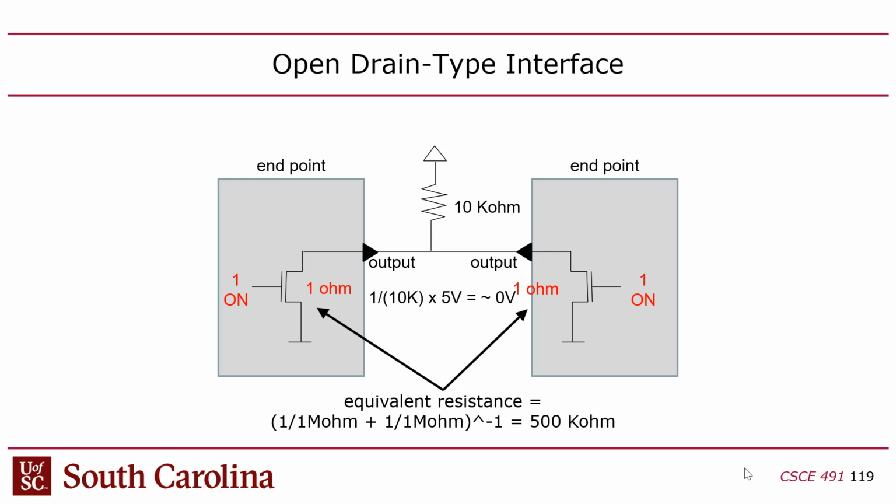Now I have another voltage divider, which is 10 kiloohms on one side and then 2 parallel 1 ohm resistors on the other. Essentially, I get pretty much the same amount of current through there. Well, I get double, basically, right? So I had half a milliamp originally, and now I have another half a milliamp that comes down through the other one. But it's not a big deal. It's not catastrophic, because now I've got 1 milliamp in total, right?